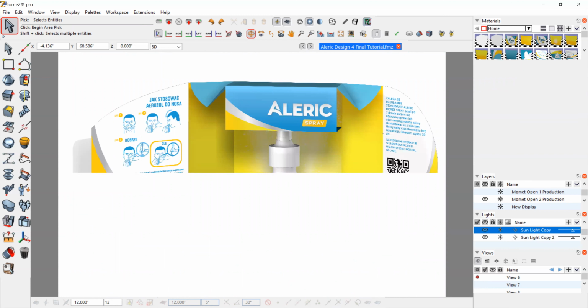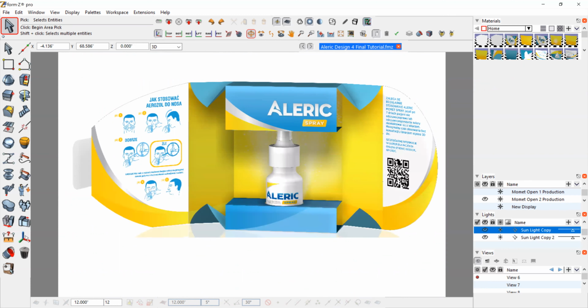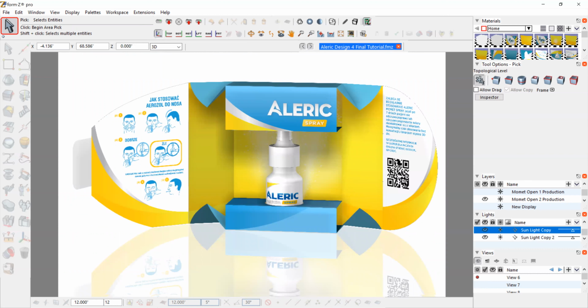So here the shadows are coming in a little bit more. You can see these soft shadows. The closed box really didn't have a lot of geometry that the shadows would be needed for, except for maybe a little shadow on the deck on that round surface. I didn't want to use that this time, but in here the shadows are on, so you can see them. It's really helping us see some of that geometry inside, and the bottle is set back, and so I think this looks pretty good. The reflective surface is a bit overwhelming, but like I said, I could back off on that. I think I'm at 20%. You could go down to like 12 and make it very subtle.